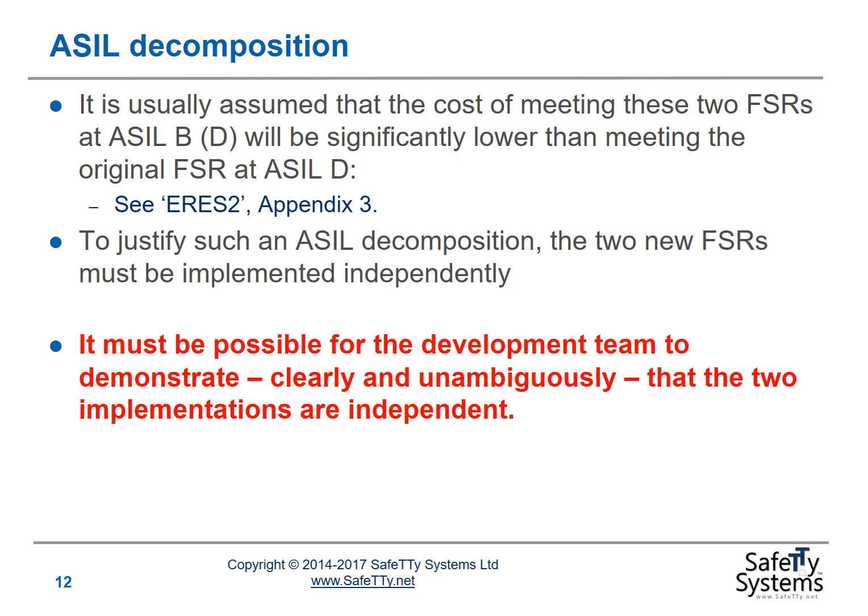To justify this type of ASIL decomposition, the two new FSRs must be implemented independently. And it must be possible for the development team to demonstrate clearly and unambiguously that the two implementations are independent.